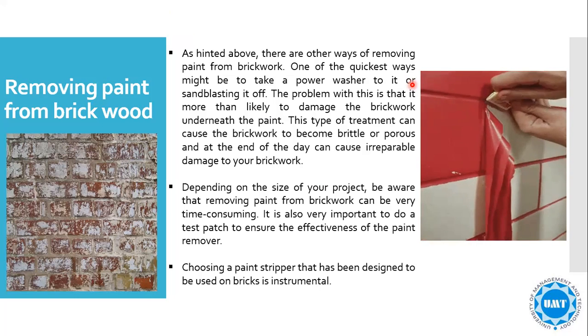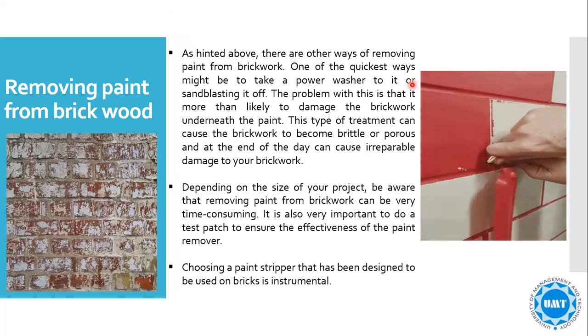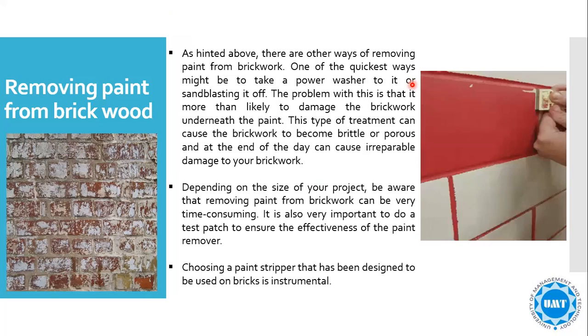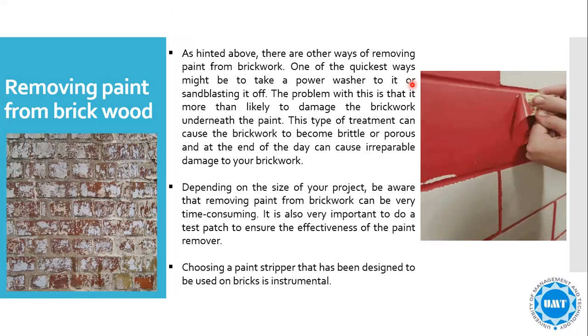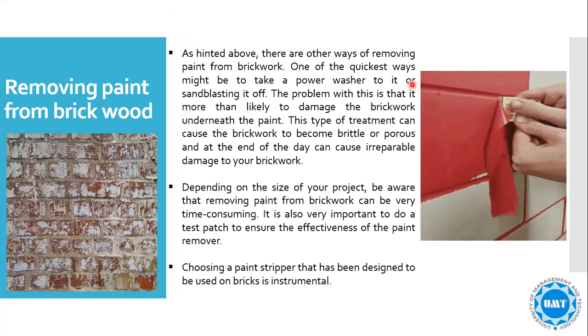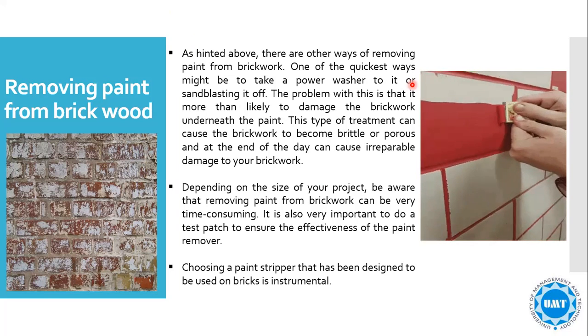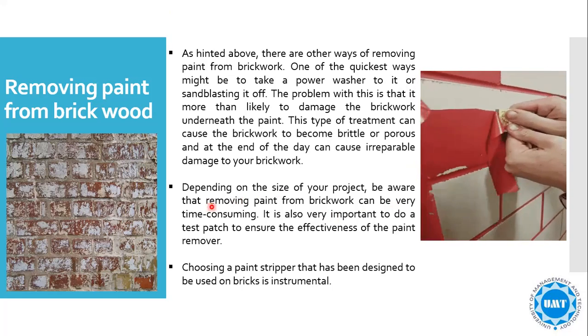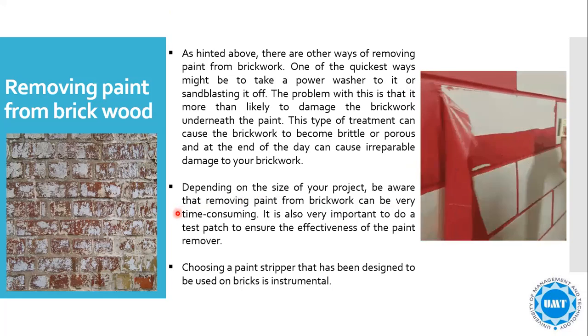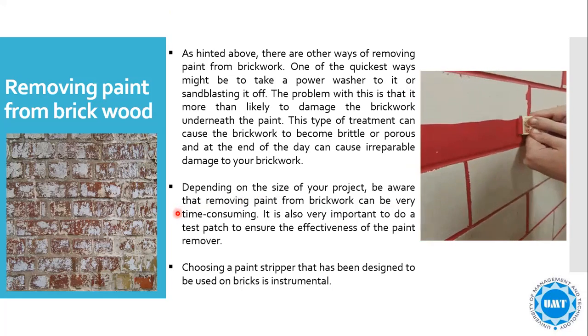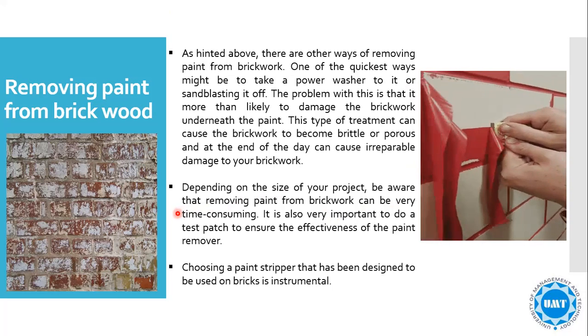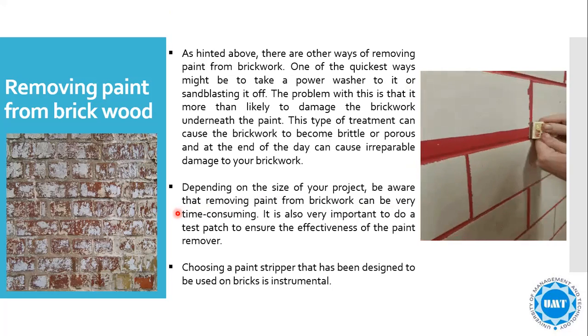This type of treatment can cause brickwork to become brittle or porous and, at the end of the day, can cause irreparable damage to your brick. Depending on the size of your project, be aware that removing paint from brickwork can be very time consuming. It is also very important to do a test patch to ensure the effectiveness of the paint removal.